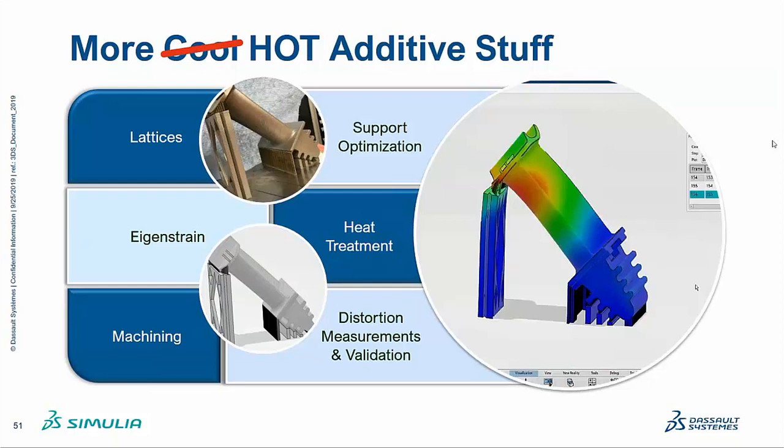And as a final note, on this page, which we haven't talked about at all, is the fact that machining comes into play. Machining is not simply the matter of taking away material for removing the part once it has been printed. You can also consider cases such as hybrid additive manufacturing, where layer by layer or a number of layers are being manufactured, upon which a mill comes in and makes sure that the geometry conforms to a specific tolerance level, and that in turn will also induce heating and so on.